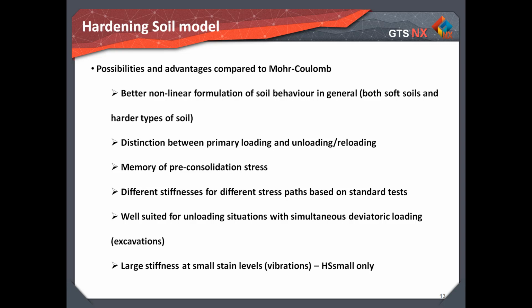Well suited for unloading situations with simultaneous deviatoric loading, for example, excavations. And lastly, large stiffness at small strain levels, such as vibrations, but this effect is only with hardening soil with small strain.